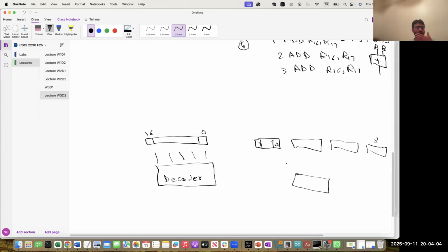You don't know whether the next instruction you read will be 1 byte, 2, 4, or 8 bytes. So you will have to read all 64 bits. Then when you look at the opcode of that instruction, you find out that you read 64 bits but this instruction is only 1 byte, so you need to discard the rest, and you don't care about them, right? So your decoder will become more complex.